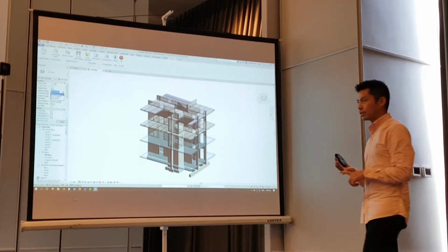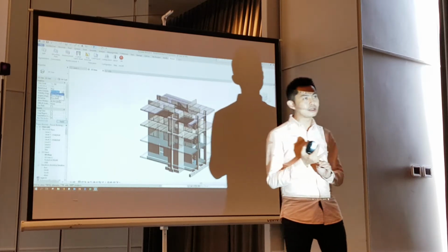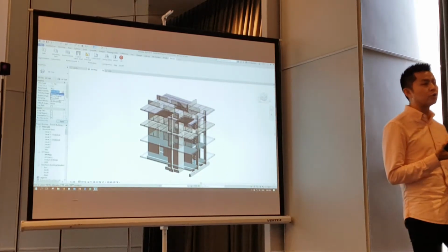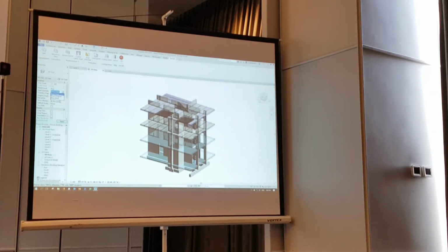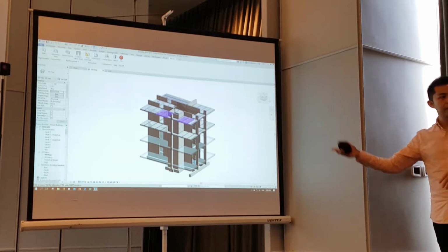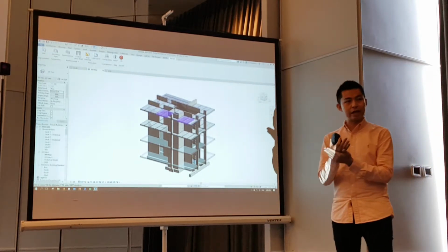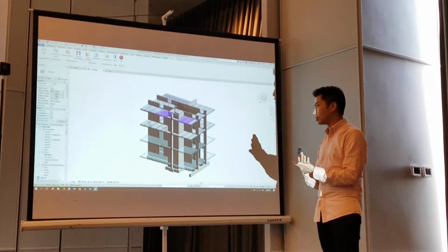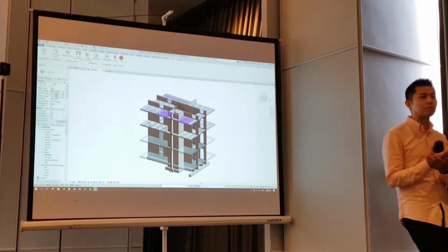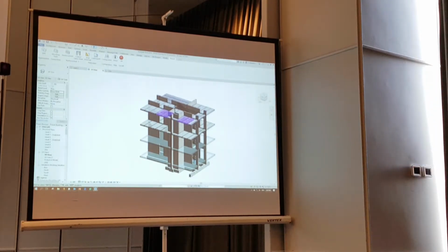If you click on the parts assembly, you should be able to see show parts, show original, or show both. Alright? If you show both, it means that you are showing the design models and also the fabrication models. Okay? So how Pre-Cast works again is it converts your design models into a fabrication model. That's why you still have 2 things over here.